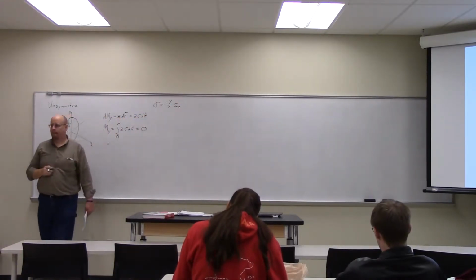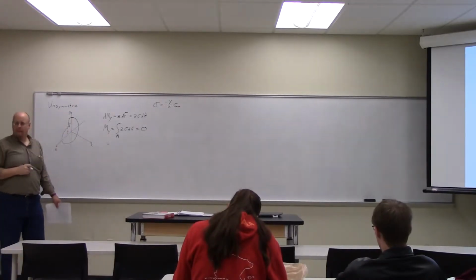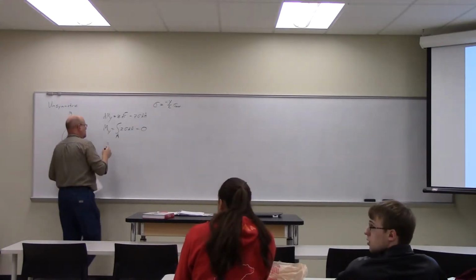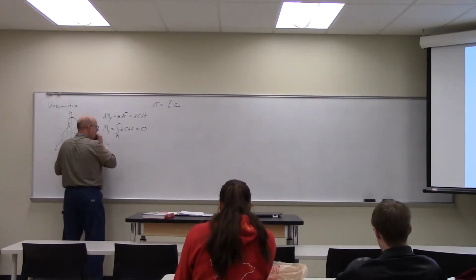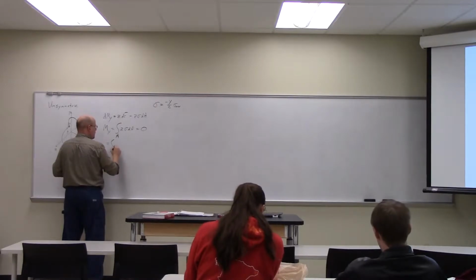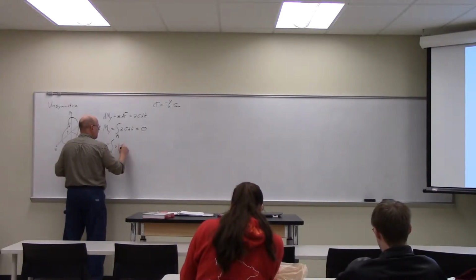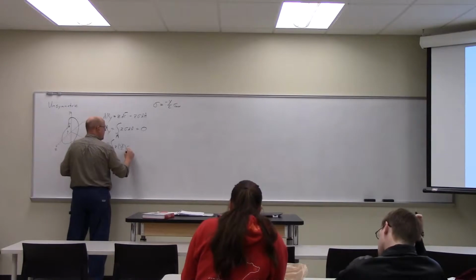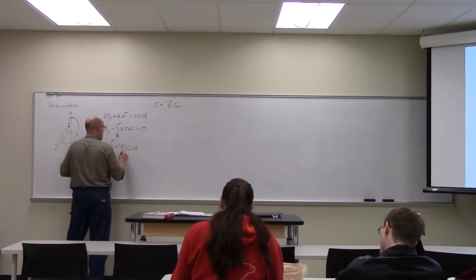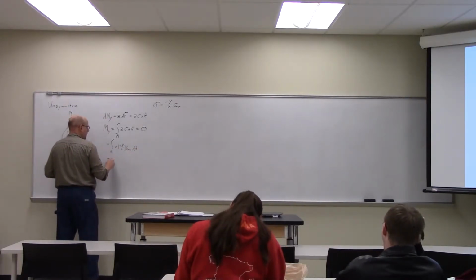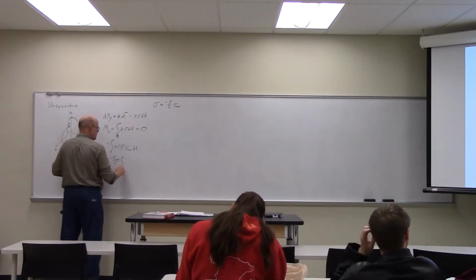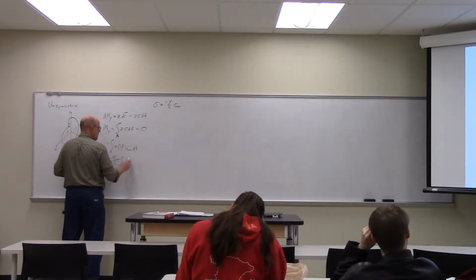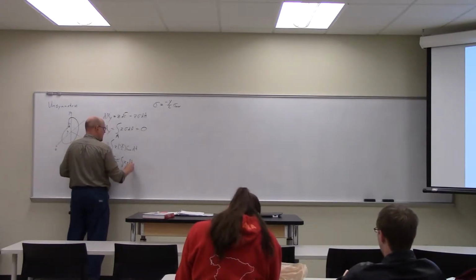Okay, so it's some fraction of the maximum. So we end up with the area integral of z times negative y over c sigma max dA. The sigma max and c come out because they're constant, and we're left with the integral of zy dA.